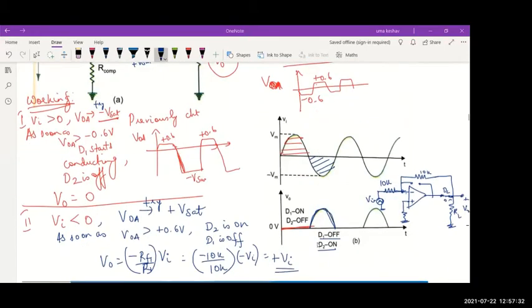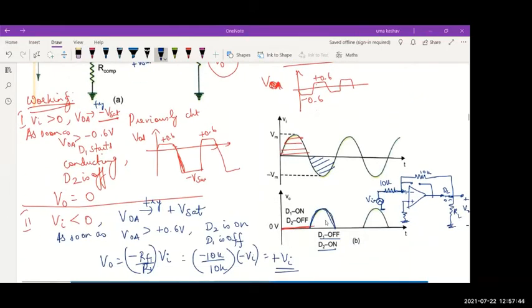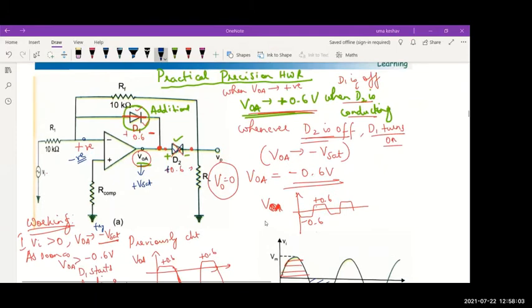Your output behavior changes according to where you have connected the input. Here, input is connected to the inverting terminal of the op-amp. You always have an inverted behavior. That is, I'm going to get the negative half rectified to positive half cycles at the output. What if I wanted the reverse? Positive half cycles becoming negative half cycles and rectified. What should you do?